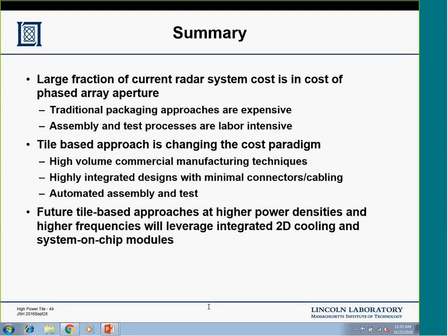The tile-based approach is a very interesting and capable way of doing that, and we're demonstrating that at moderate power levels and lower frequencies. And I think the interesting challenge for phased array engineers going forward is to migrate those things into higher frequencies and higher power densities. And I think that things like integrated two-dimensional cooling and a highly integrated system on chip will be the path forward. Thank you.